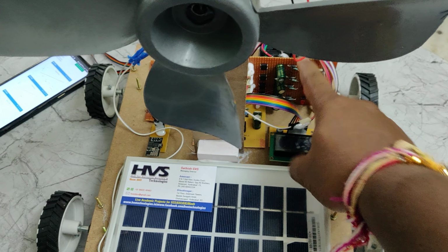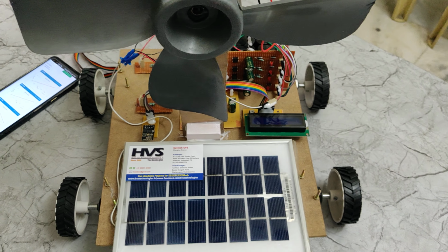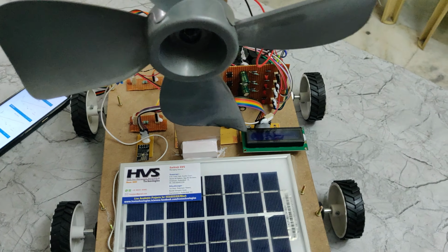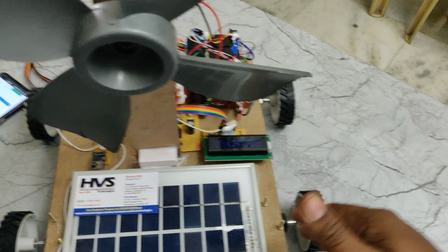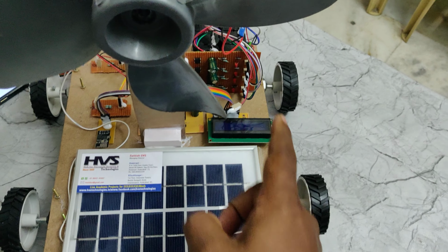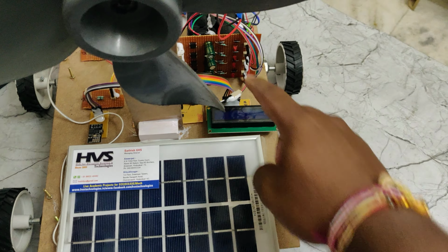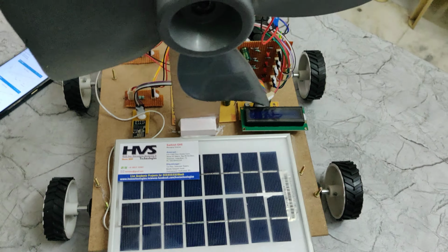The purpose of these diodes is that whenever the battery is fully charged, the battery becomes the high potential one and the generators become the low potential when there is no power available from them. Then, in order to block the current flow from the battery to the generators, either wind, solar or dynamos, these diodes act as unidirectional current flow. They will block the current flow from the battery to the sources.